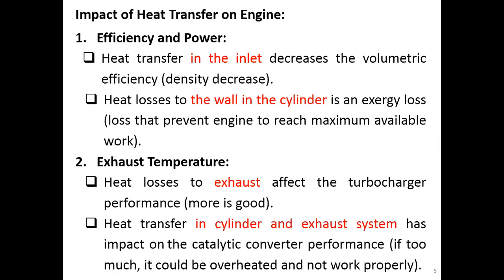This will help you solve the problem of why your engine cannot get more work than you expect. Heat loss to the wall is considered an exergy loss here. So this is the impact on efficiency and power, right? If it happens in the inlet, the volumetric efficiency decreases. And if it happens at the wall of the cylinder, it's an exergy loss here.